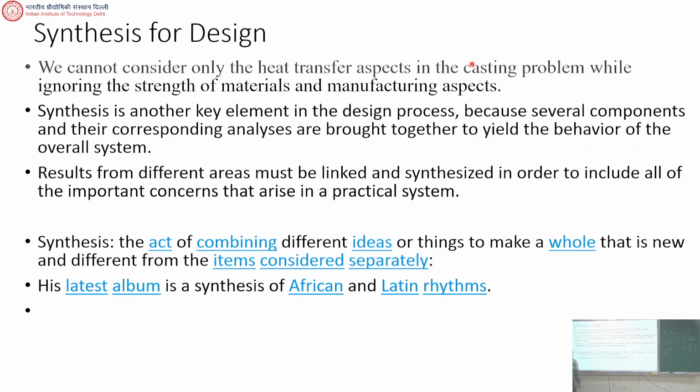They will also look at the structural aspects, the stresses, and maybe also some vibration issues. So once you make your designs, you have to sit together and put everything together and also see whether those things can be properly manufactured, whether the heat exchanger can be easily cleaned, because the heat exchanger will get fouled over a period of time. Then how to clean that? Everything has to be put together. Otherwise your design will not work. Design is not just thermal design. So that's why you need synthesis.